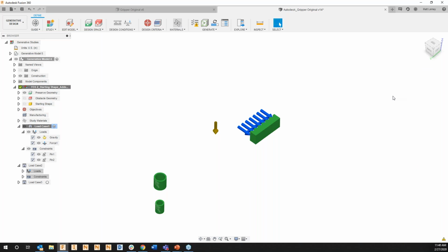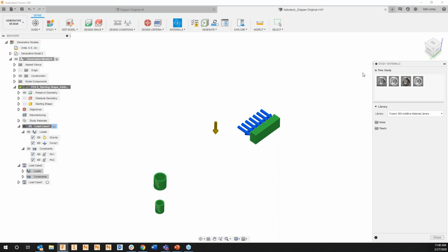And then finally, for our material selection. So the idea within generative design is that we don't want to just optimize for one material type and one manufacturing option. We really want to apply a wider range of options to then make more informed trade-offs. So currently within the solve, we have stainless steel, aluminum, titanium, and then another version of aluminum in 6061. So within generative design, we can put up to 7 materials at the same time, multiplied through all of those different manufacturing types to give us that range of outcomes that we talked about earlier.